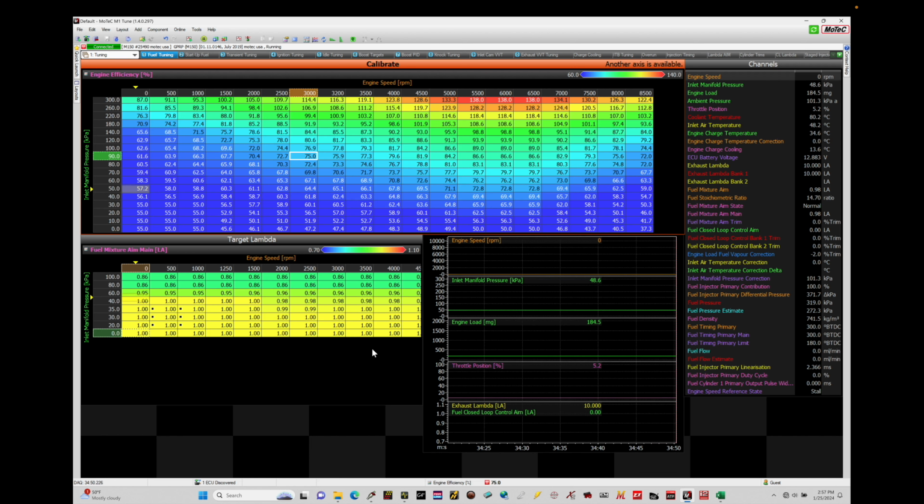So we have things like our charge cooling, fuel injection timing, and we have our fuel film that we actually have to go in and check and test when the secondary set of injectors are working and spraying fuel into the engine, in order to properly model all of this within the Motec. So we have a perfect spot-on air and fuel model.